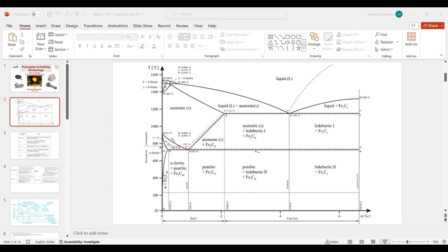We are going to heat treat it beyond upper critical temperature, and we are allowing the sample to cool down in the furnace itself. So whatever stress is present there is going to be removed from the sample by the grain refinement process.